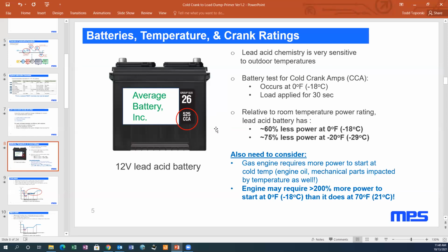I think the other difference that we see is also in certain regions. We see, like in the US, for example, a lot of the cold crank specifications tend to be more in the 4 or 4.5 volt range. Some of them are in 5 volt range. In Europe and sometimes in Asia, we see requirements that get even lower than that.